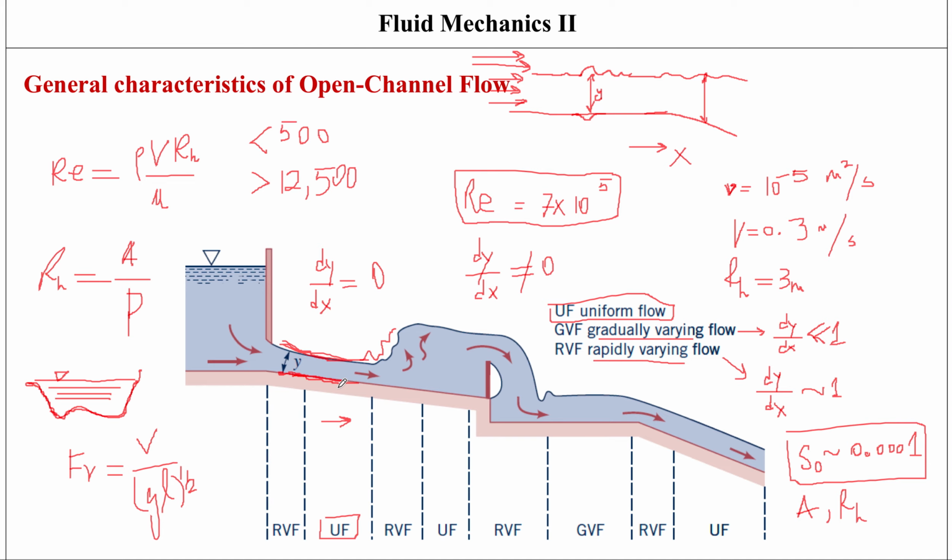So then you need to look at what that character is, and usually the character of the material is given in terms of N, which is a coefficient that is usually available in the literature in the form of tables, and it's called the Manning coefficient. Okay, so the value of N is something that you need to see from the literature.